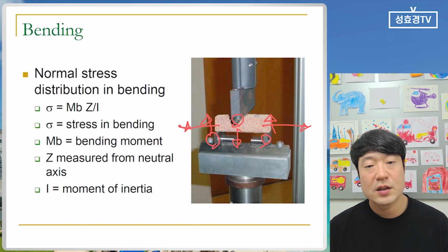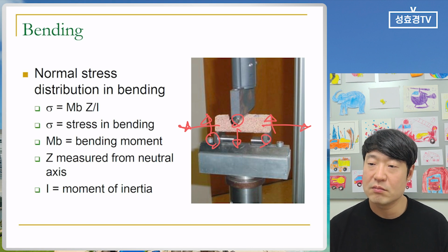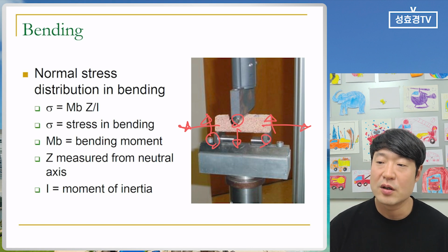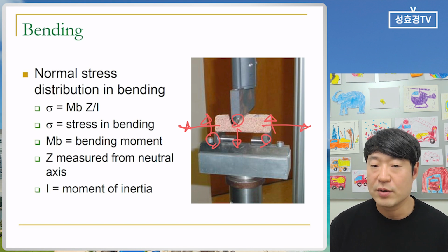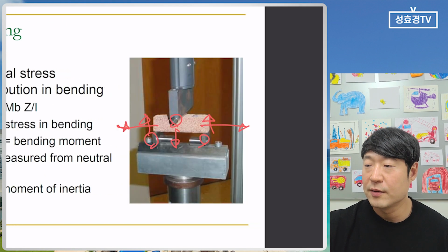But bending is not as harsh as the tensile test. I recommend that the first time, the tensile test is the best to understand this. But it depends on when you want to do the bending test, and if you have an application for bending, then it can be used for that.